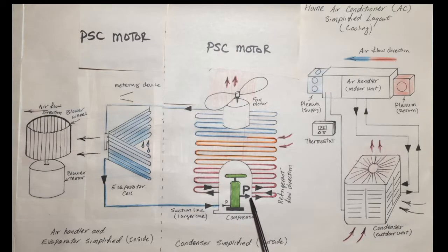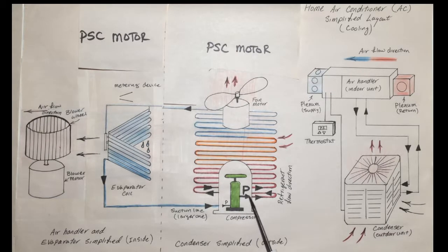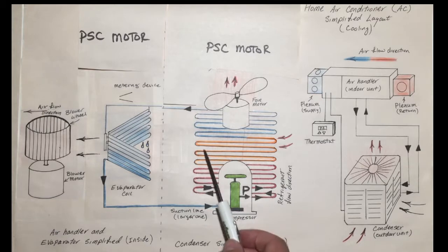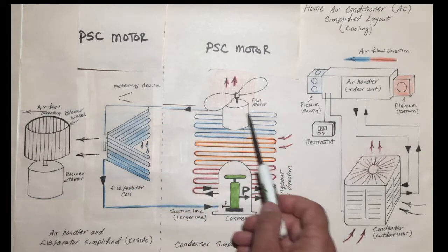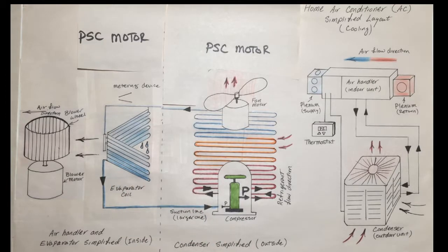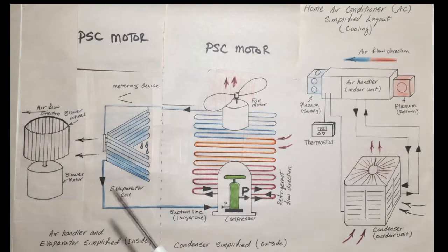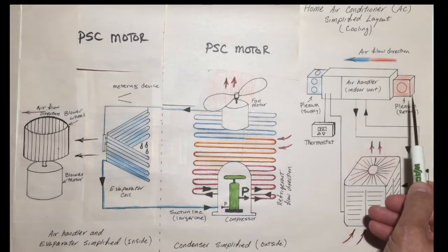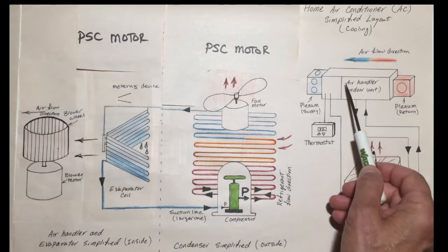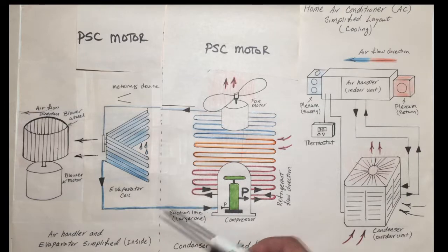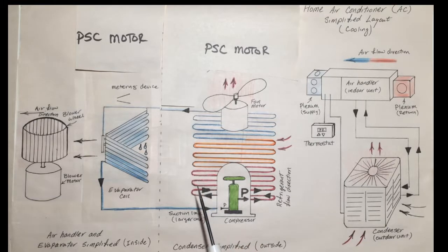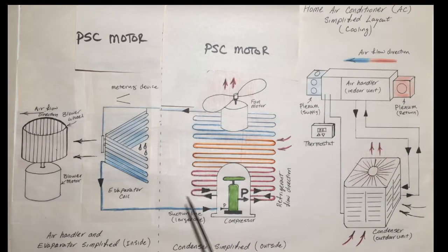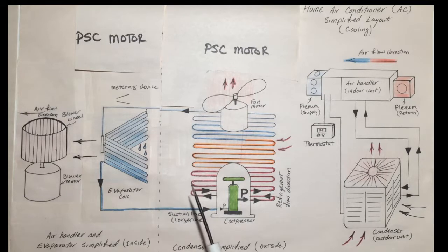The compressor increases its pressure and acts as a pump to recirculate that refrigerant through the system again, and the cycle continues. So this is how we're basically removing the heat that we don't want inside of our conditioned space with these components. Again, this is simplified. So now let's take a look at some of the components that fail frequently. I say frequently, I should say more than others.